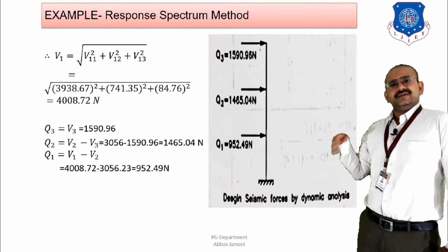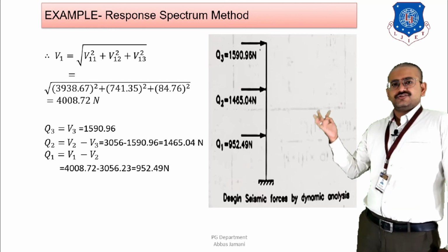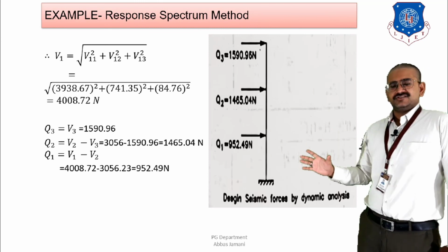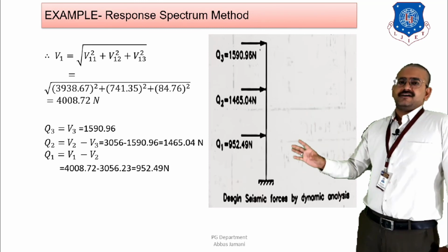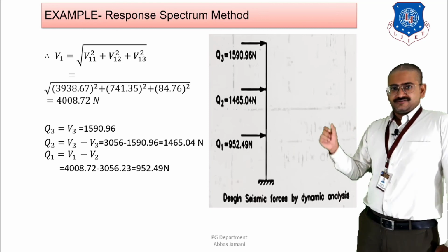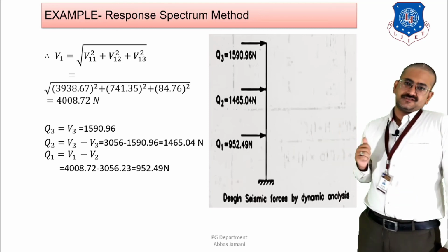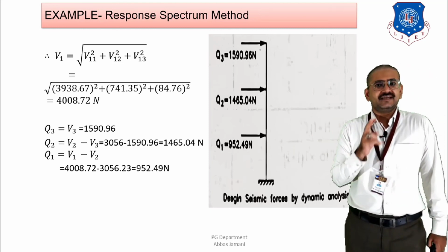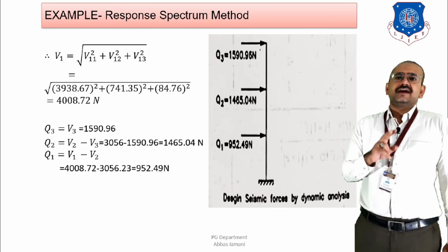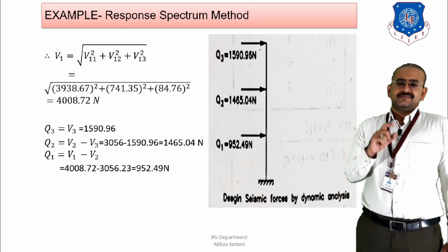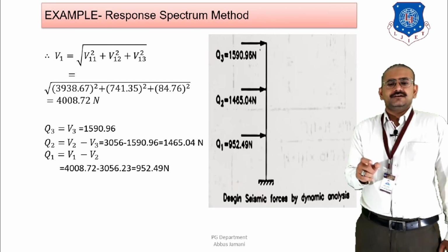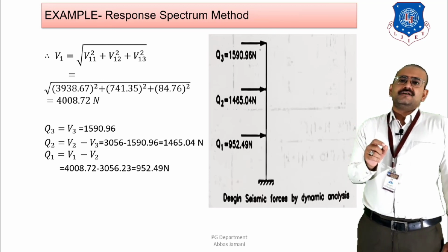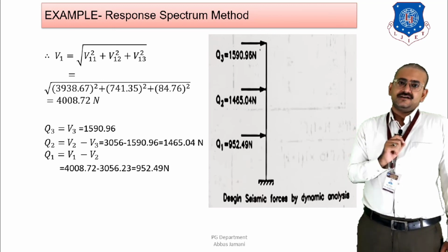And if you talk about base shear, then it is going to be reversed in nature, where base shear is going to be maximum at the bottom and least at the top, right? The same kind of behavior can be obtained from the CQC method also. So these are both independent methods based on which you can do the modal combinations, and based on the modal combination you can calculate the value of lateral force and the value of the story shear accordingly.